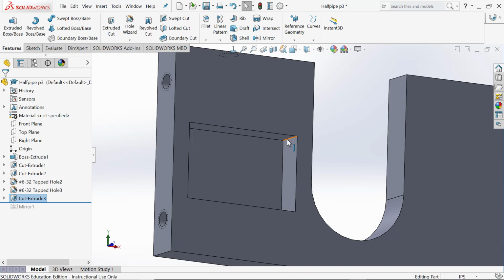If you do accept on your cutting, now if you did boss extrude instead of cut extrude, that'll make sure you don't have a hole because it didn't cut, it added, right? You don't want to do that. Is there any chance you did boss extrude, those of you that don't have an indentation? It does say cut extrude? Well, edit the feature. Check that you're offset from surface. Make sure you chose the opposite surface from the side that you drew the sketch on.